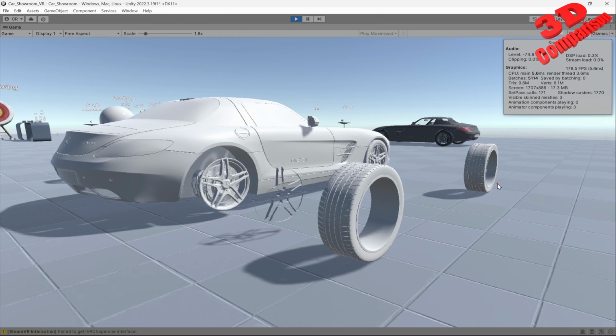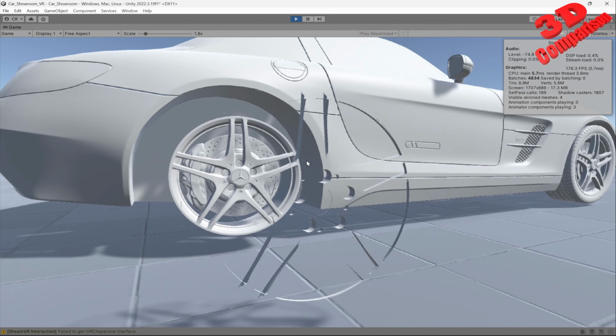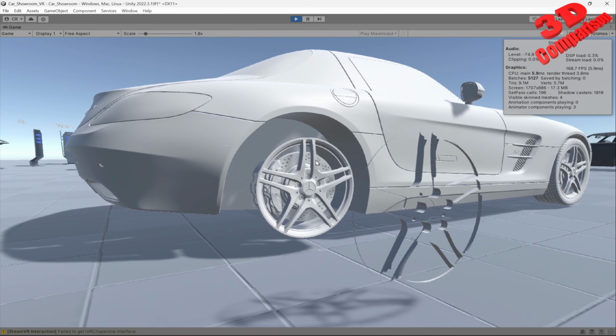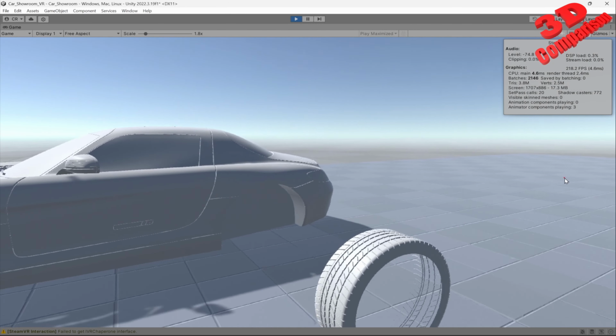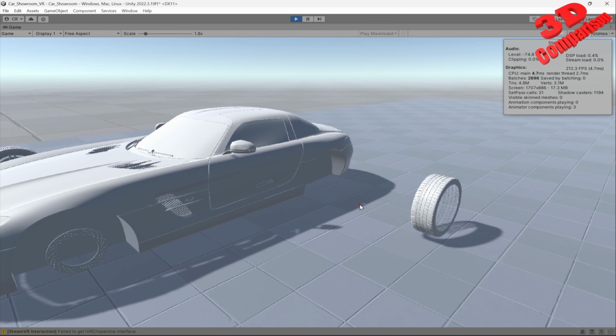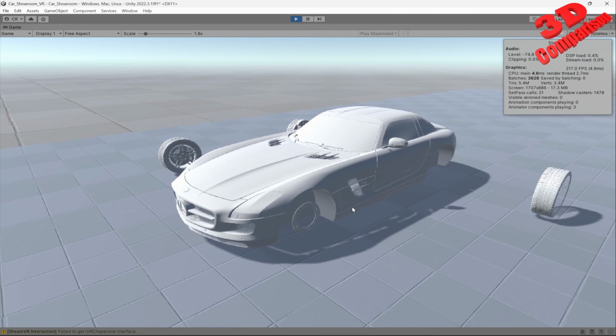We can also change that within Unity using a double shaded material, or we can make sure that the orientation from Blender is defined, or we can just add a 3Dify tool. So I'm going to create an individual video regarding this, but I'm going to start initially with the exploded view of the car, how we can set that up. For example, we can have the elements of the wheels translated over here to the sides, and maybe the chassis and everything else will go up on the Z-axis.